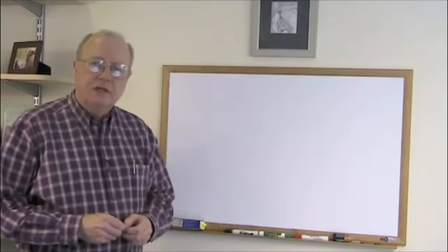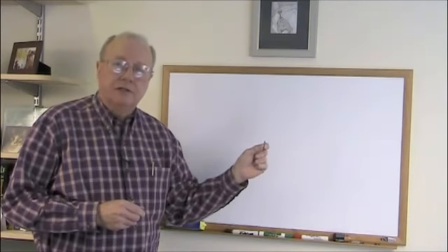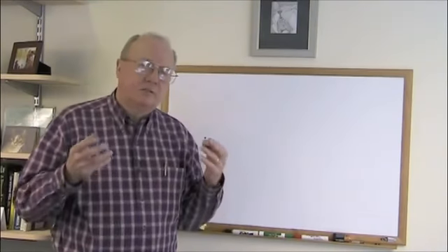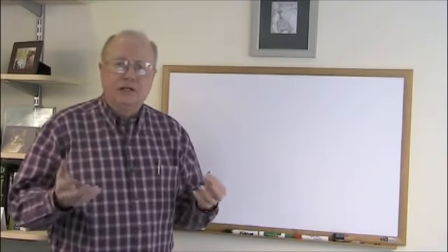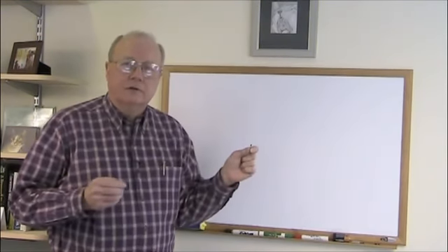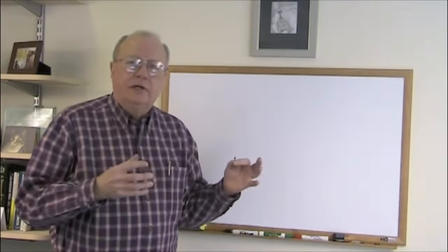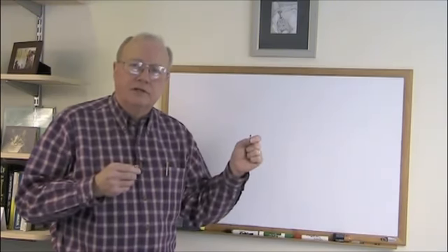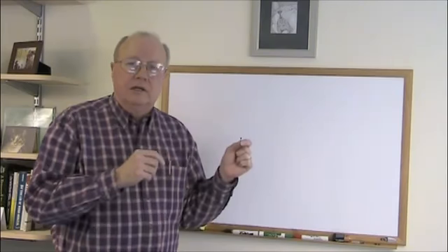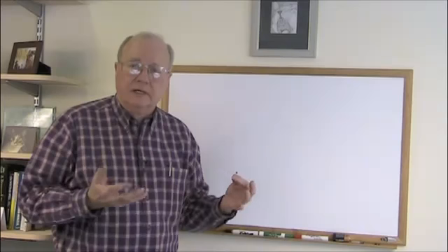In this video segment, I'll describe how we can use small transistors like this one to drive LEDs, turn them on and turn them off. You might ask, well, why do I need a transistor? I can just supply some current to the light emitting diode and turn it on and take the current away and turn it off. Well, transistors can take a small amount of current and turn it into a large amount of current. It doesn't actually create that current, it just switches that current on and off through the transistor. So a little bit of current going into the transistor or coming out of the transistor can control a much larger amount of current flowing through the transistor and thus your LED.